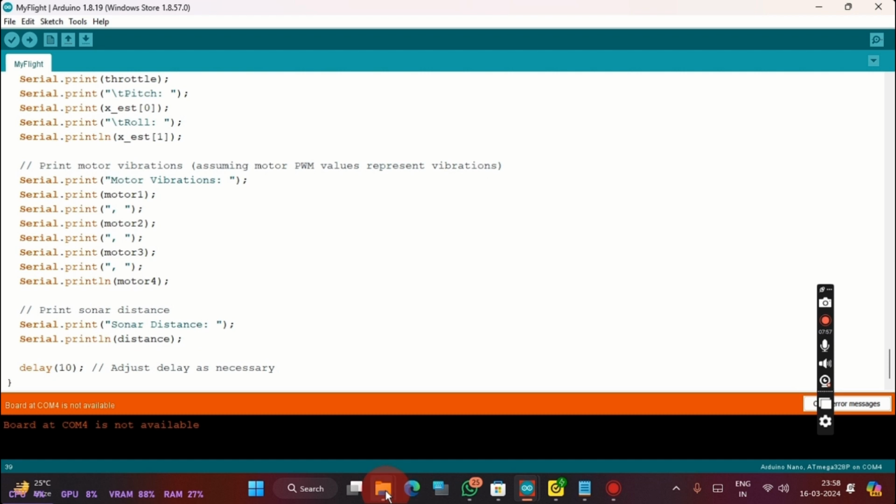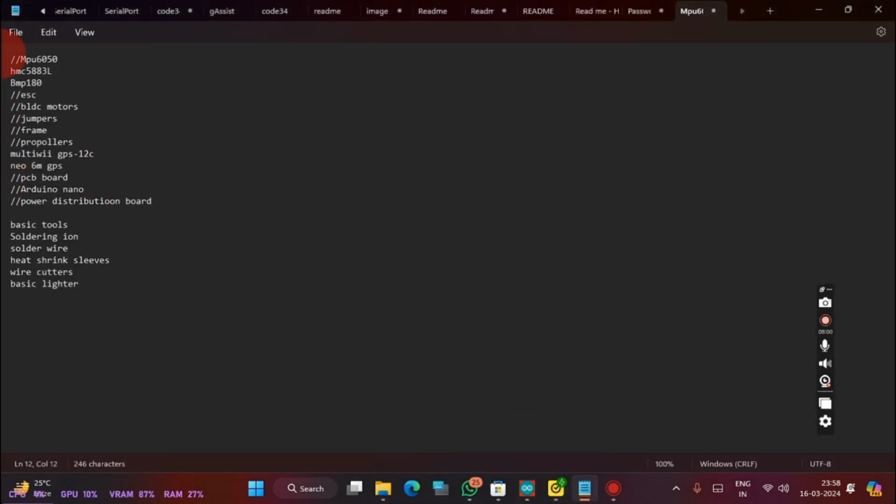Okay, and also one more thing. Here, if you go to the HMC file, this is a magnetometer, accelerometer, and this BMP180 is our barometer. So this HMC5883L, what's the problem with this? You will also get many products from the market named QMC5883L, but HMC5883L is the real, original one, manufactured by Honeywell, and it's not fairly available in the market now. So you will mostly find QMC5883L. The problem with both of these is that QMC5883L has a different I2C address and HMC5883L has a different I2C address. So I will develop my code for HMC5883L, not for QMC.